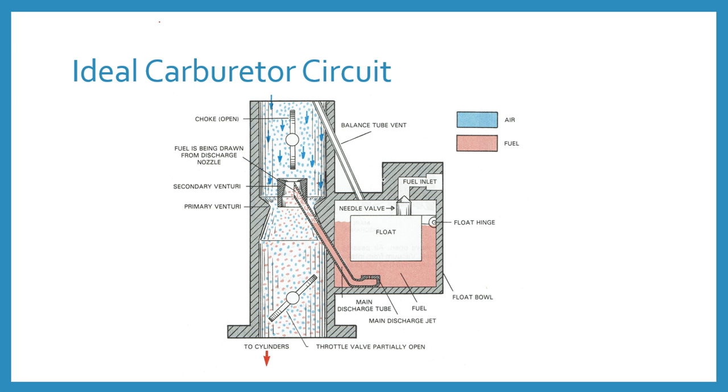This is because there is no vacuum above the throttle valve, but a strong vacuum exists below it. Here an idle mixture adjusting screw is provided in the idle port, which regulates the amount of air and fuel mixture that can be drawn into the intake manifold.